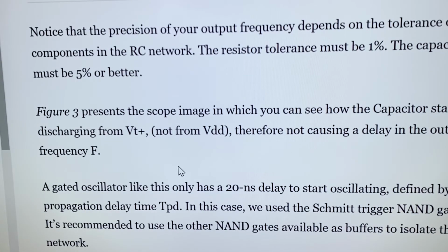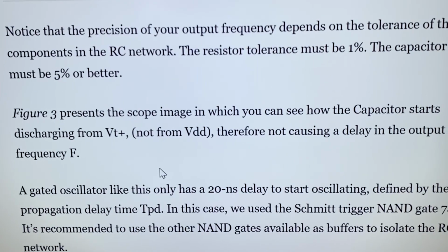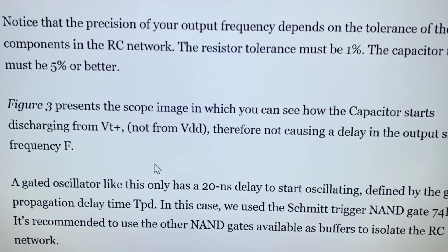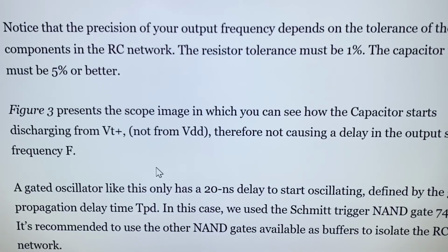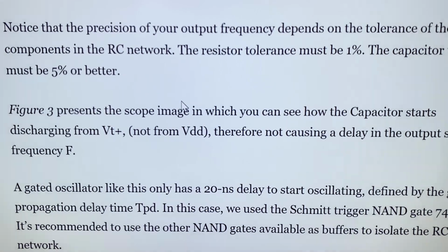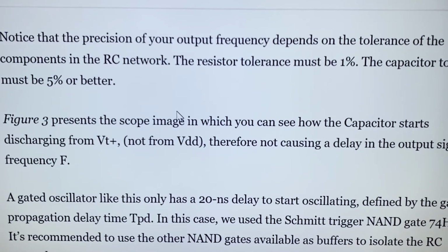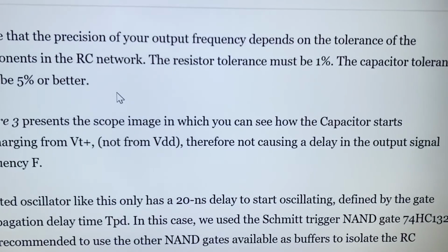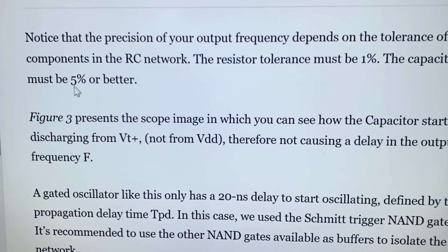So another issue that I have always noticed in these designs is that you always have to consider the tolerance of your elements. Sometimes students tell me, Professor, I'm not getting the frequency I was expecting. And when I see their designs, they're using 5% or 10% resistors, most of the time 5%. And the capacitor tolerance is the most critical part, because sometimes you're using 20% tolerance or even higher.